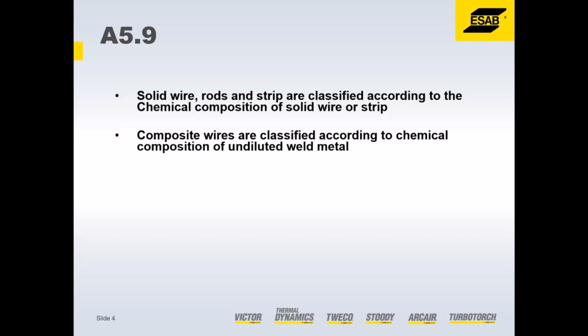So if you have a pressure vessel that needs to be 2 inches thick for strength, but you don't want to make the whole thing out of stainless because that would be expensive, you can clad the 2 inches of carbon steel with a stainless, and then you could have the corrosion resistant properties of the stainless, and you can get all your strength from the carbon steel and not have to make the whole thing out of stainless.